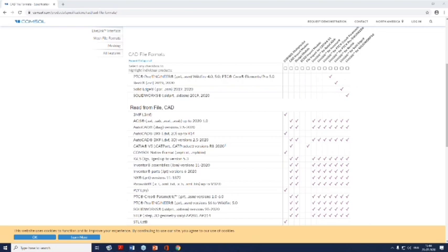How to create a shorted circular coil of 10 turns and give AC current of 1 ampere at 10 kilohertz. See, we do not do this through physics completely. COMSOL has various features under each physics. Just for an example, when you're talking about the circular coil of 10 turns, you can directly create the circular coil maybe using the torus feature, or you can just create one circular surface and then using the revolve operation you can create that circular ring.